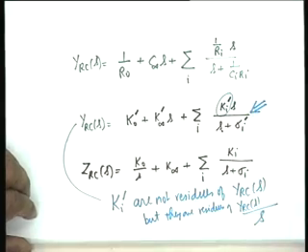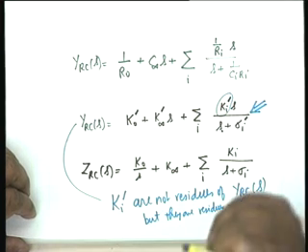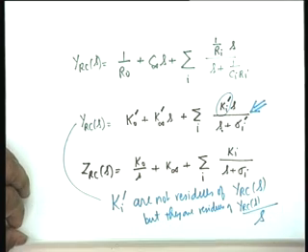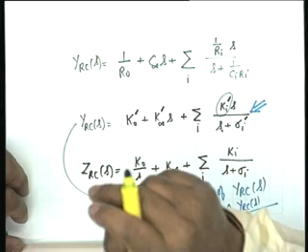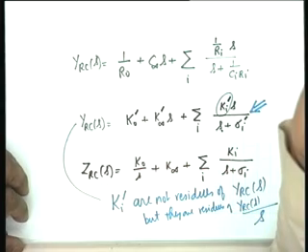The major conclusion that we wish to derive from this expression is about the poles of YRC. Where are they located? Obviously on the negative real axis. Could there be one at the origin? No. There cannot be a pole at the origin of YRC, but its zeros are still on the negative real axis. I am sorry, the poles.